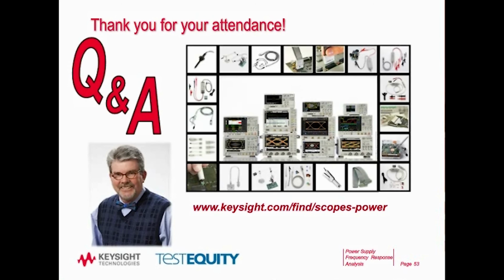Okay. How much oscilloscope bandwidth is required for the measurements? Well, all the measurements I showed today, we were only doing the frequency response test up to 20 megahertz, and often they're done much lower than that. A 100 megahertz scope would have been more than enough for all of these tests. Now, that's for these tests. Typically when you get a scope, you don't buy a scope specifically for one test, such as the frequency response. You buy it for other things. So, for frequency response analysis, bandwidth's not an issue. You want to evaluate what your other measurement needs are. Maybe if you're trying to measure switching loss, you may need higher bandwidth. Or if you're doing some higher speed digital circuitry, you may need higher bandwidth.